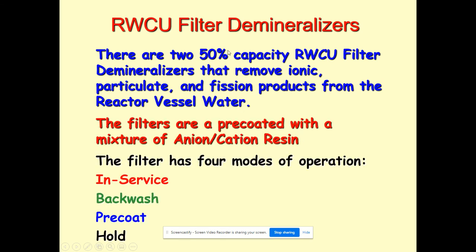So there's filters in there, and they each take about half the water that's going through. So both of those need to be running at the same time. You can go down to one for a little while while you're cleaning it off, but then you're only going to be at half capacity.